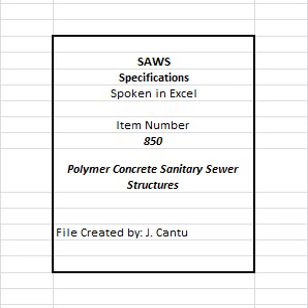4. Prior to performing the test, the contractor shall plug all lift holes and exterior joints with a non-shrink grout and plug all pipes entering the structure. 5. No grout shall be placed in horizontal joints prior to testing. 6. Contractor shall use a minimum 60-inch LB torque wrench to tighten the external clamps that secure the test cover to the top of the structure.